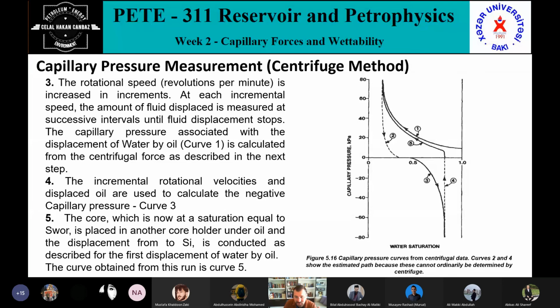Here, when the rotor is filled with the core holders containing cores placed on opposite sides, the centrifuge cover is locked, and then the rotational speed is increased by increments again. At each incremental speed, the amount of fluid displaced is measured at successive intervals until the fluid displacement stops. It works like this.